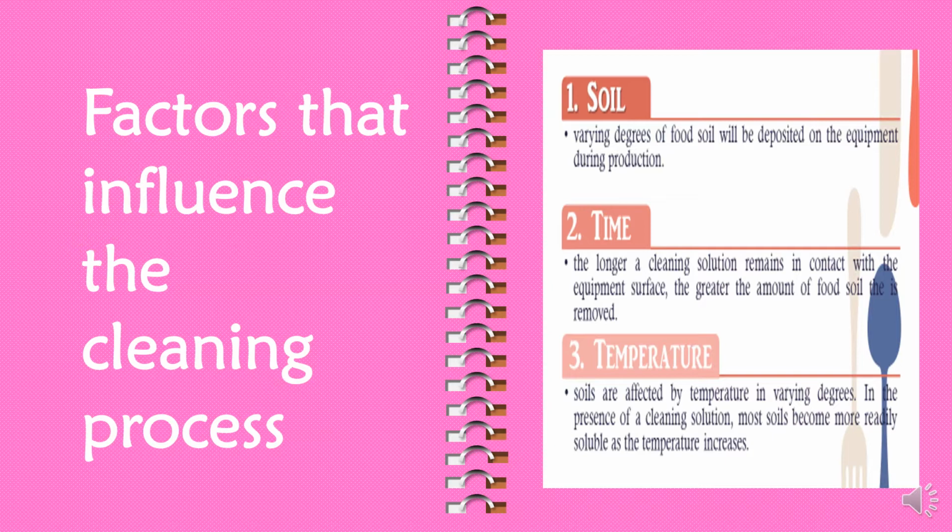The second one is the time. The longer a cleaning solution remains in contact with the equipment surface, the greater the amount of food soil that is removed. More time in contact with the soil reduces the chemical concentration requirements.